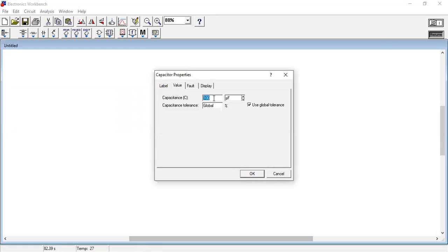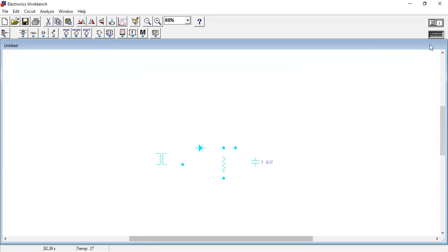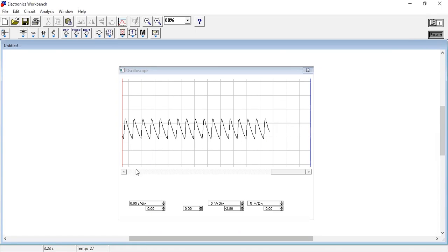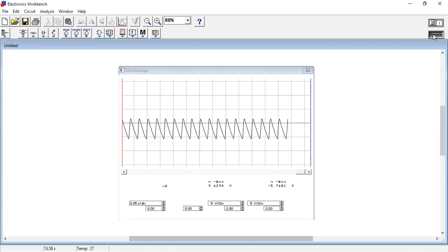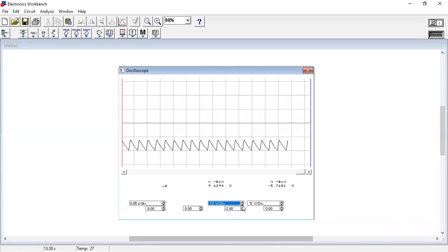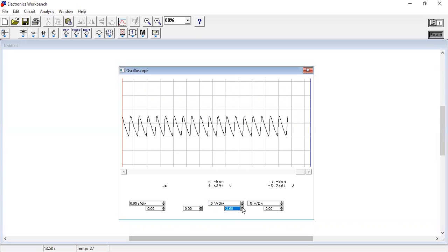So you can get the output waveforms and find the output voltage for 20 microfarad. Okay, here one box belongs to 5 volts. And here I think one box and 1.5 boxes, so 7.5 volts for the 20 microfarad. Like that we can change the capacitor values and find the output waveforms.